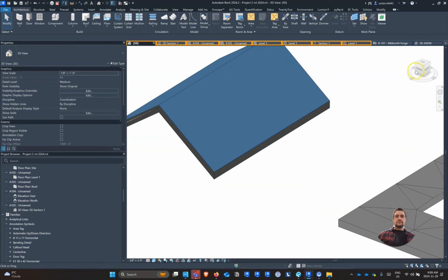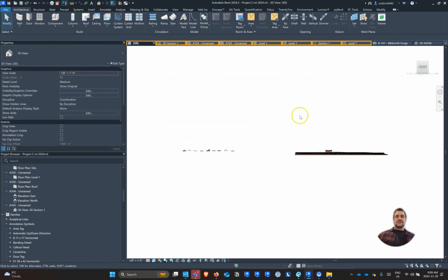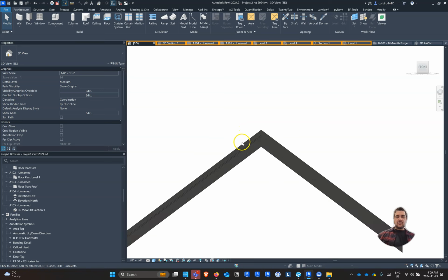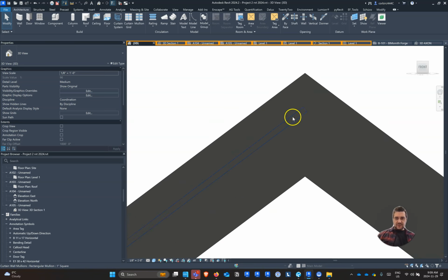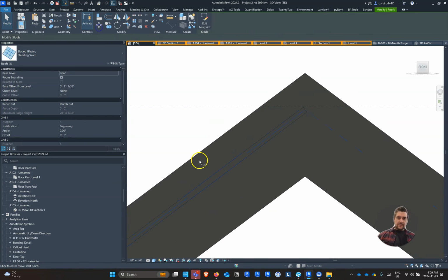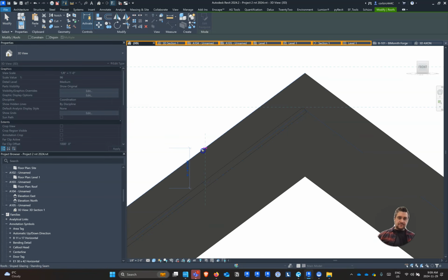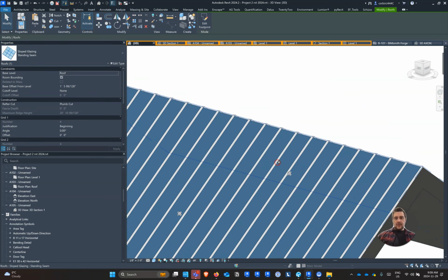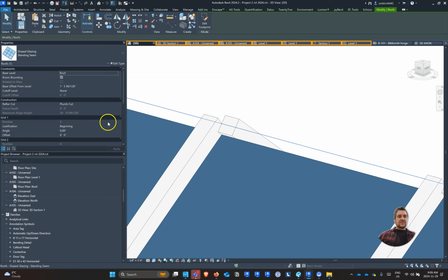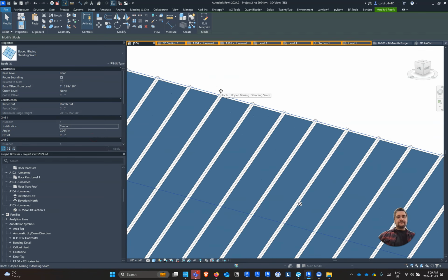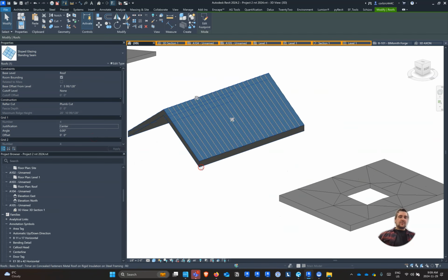And what we want to do is just raise our mullions so we can see our mullions here. So this is a curtain wall system. We'll click Raise. And with the curtain walls too, you can see how they're kind of offset. If you just change this to be center, they should line up like that. So that's a pretty cool way to bring in and create wall types and floor types and roof types.